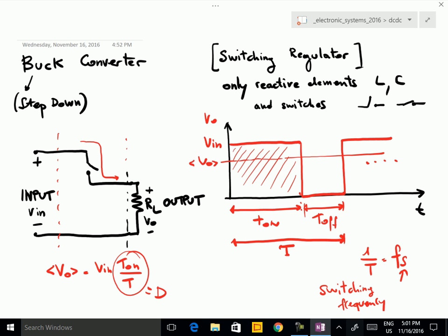If you instantaneously switch off the current of an inductive component, this voltage goes deep down, because an inductive load is inertial with respect to the current. So the voltage adjusts in order to continue to receive current, and then you typically have an over voltage on the switch that typically can cause problems.